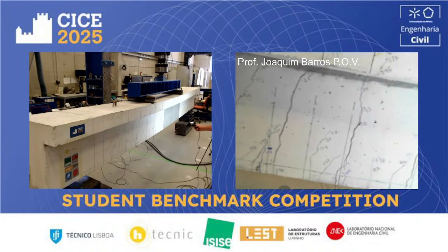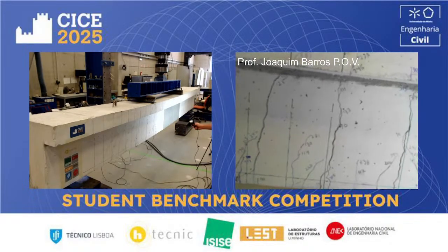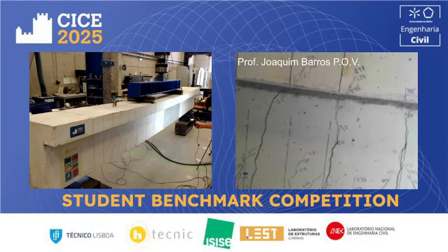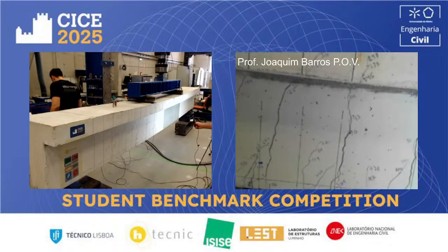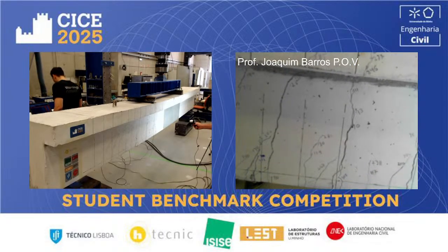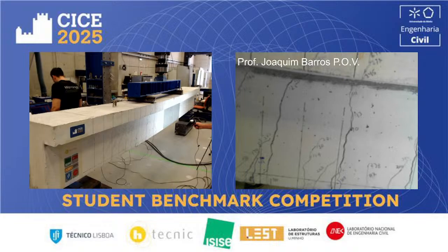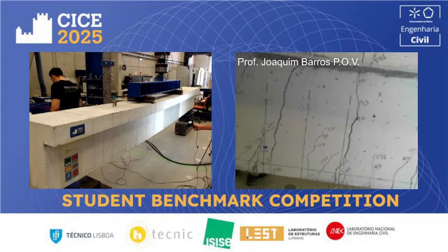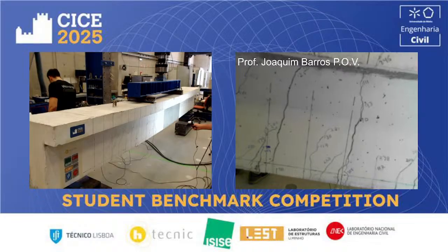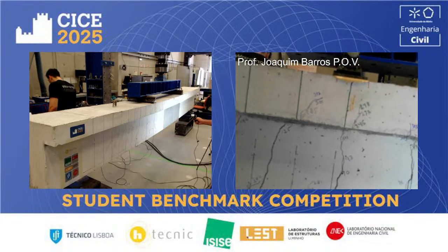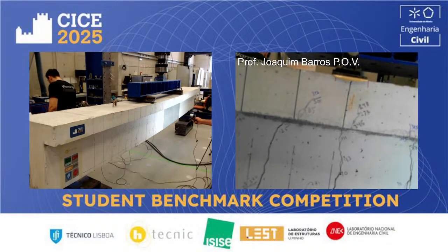So when we are now analyzing this crack, 373, the flexural crack in the loaded region is similar. Closer to the level of the flexural reinforcement, the crack width is much smaller than in the middle.